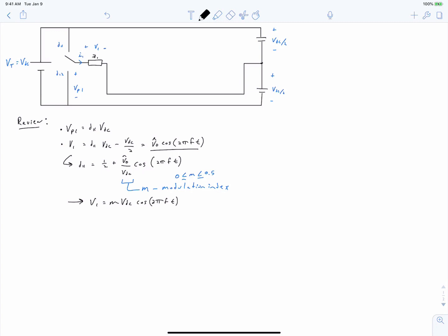we can write this voltage expression, we can put it into phasor notation, and this is a throwback to our early days in this class when we reviewed different ways to express power electronic quantities. And so we'll do this as an RMS phasor, which has a magnitude of V out hat over square root of 2, because this is a sinusoidal quantity, so we can convert between the RMS value and its peak value by just dividing by square root of 2.